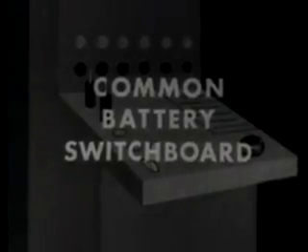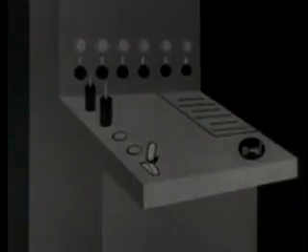This system provides for automatic rather than manual signaling, eliminates local batteries, and provides faster service through more efficient operation. Generators and batteries are eliminated at the local stations, and the switchboard provides all power for both signaling and talking. Each station terminating on the common battery switchboard has its own jack and line lamp.